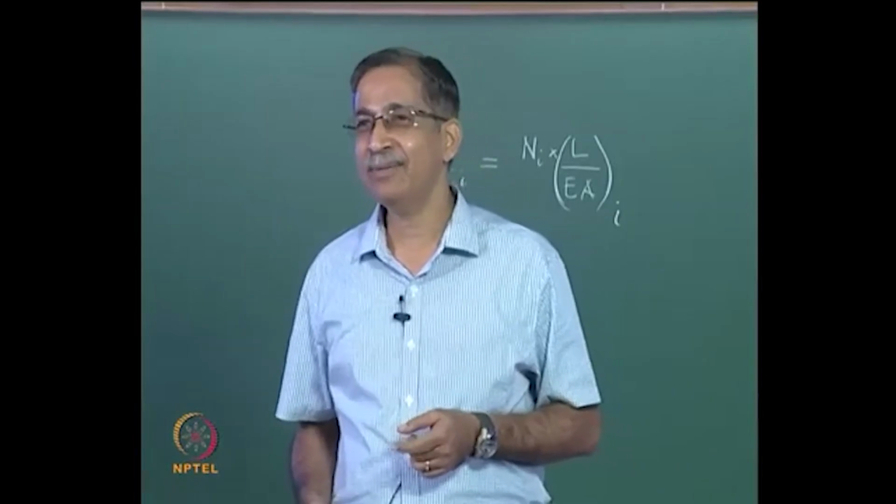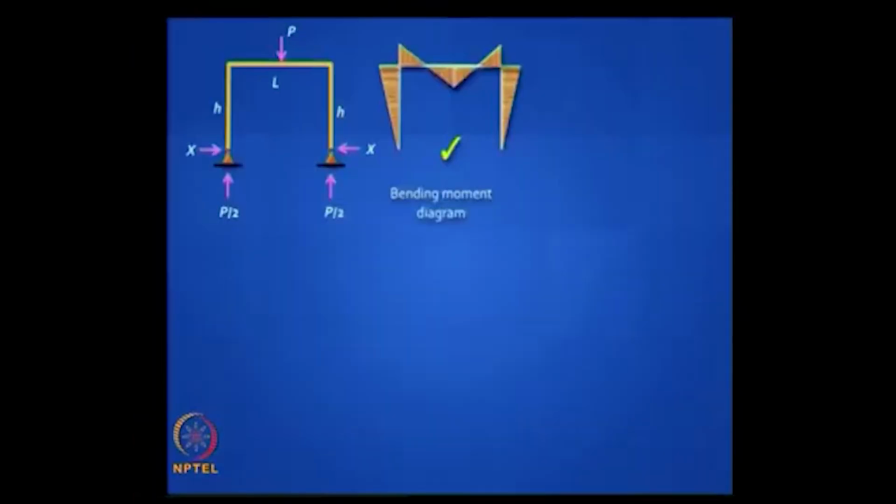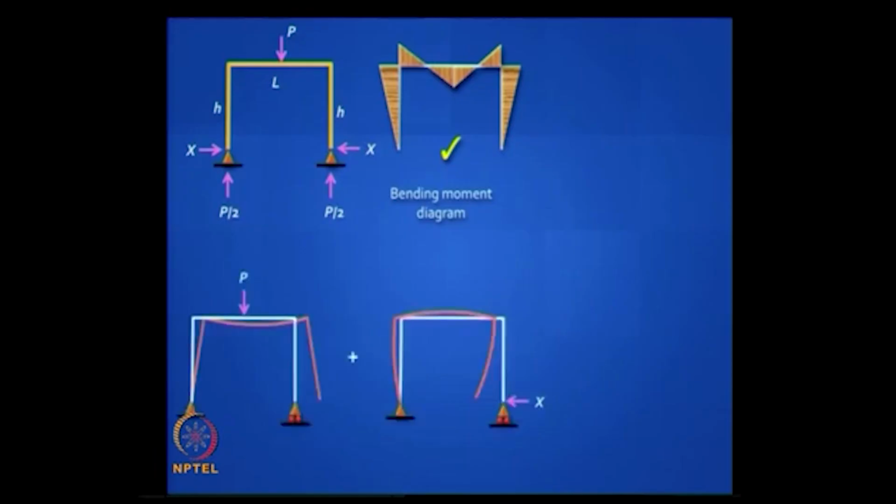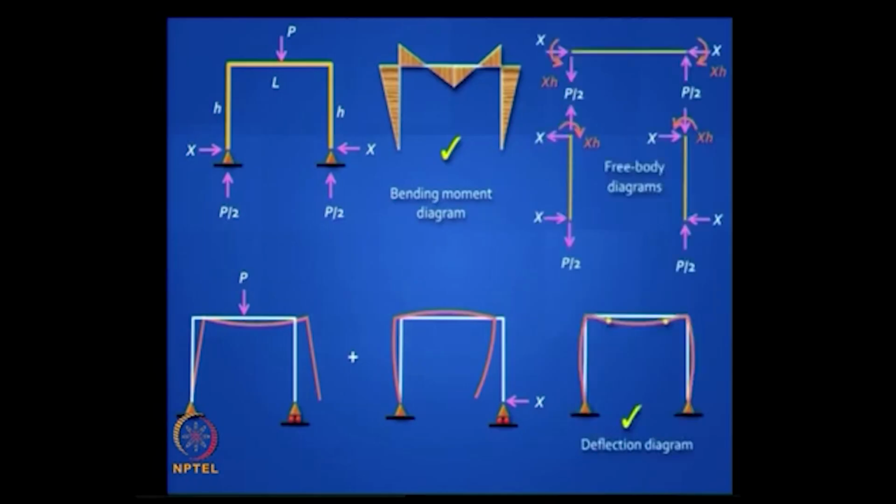Okay, now we drew this picture earlier. You will find that this bending moment diagram is correct if there was no roller support, if both were hinged, then that picture is correct. And then how to find the reaction can be done from superposition. So take the first case where it's roller, that's a primary structure, it will move to the right. So you need to apply that much force horizontally to eliminate that, and that's how this can be proved.